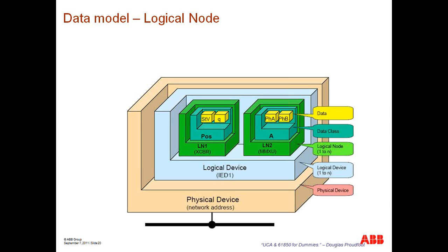Also, when looking at the validation or the testing component of the data model of devices, it makes it much easier, and less open to interpretation, to perform a validation of the data model of a device. We can go in, we can see how a breaker is modeled, we can see what are the pieces of information within that particular logical node, and then we see the format in which that information is being reported. And if everything checks off and it's per the standard, then a certificate can be issued to that particular device.